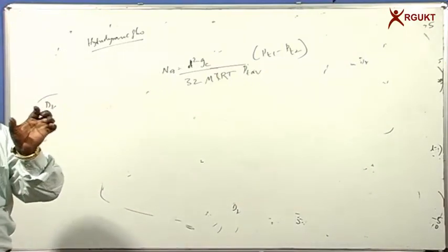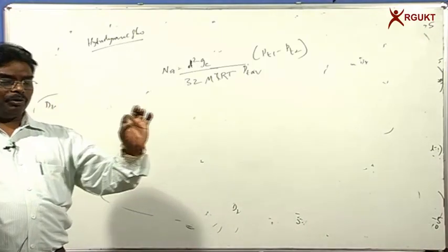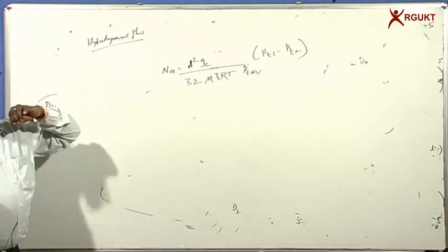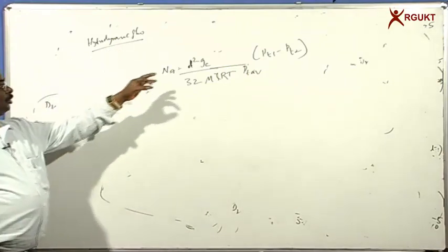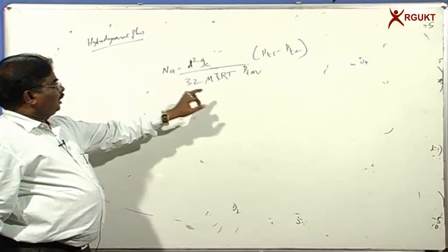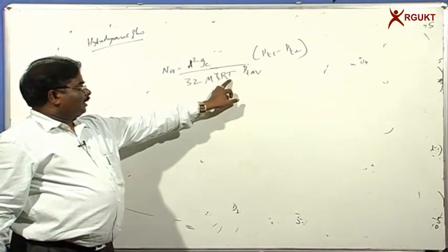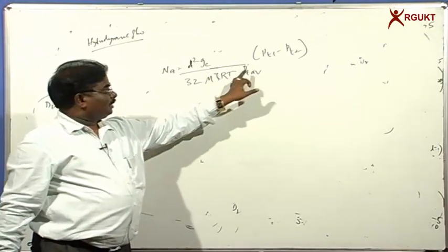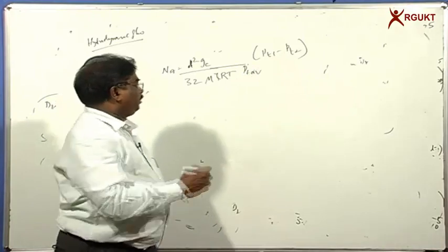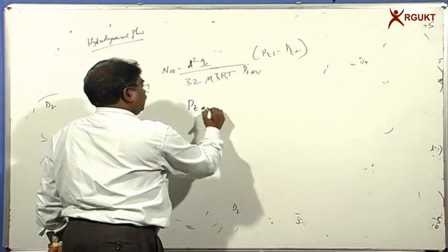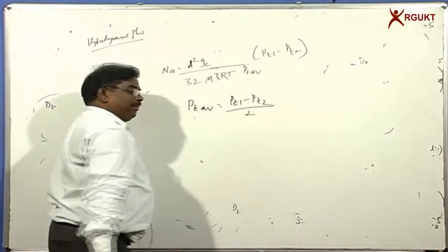The pore sizes are very, very big, and no diffusion is going to take place. The flow is taking place as if the pores are very big and as if it is a straight tube that we have. Here d is the diameter of the pore, mu is the viscosity, L is the pore length, R is the universal gas constant, T is the temperature, and P_T average is the average of the pressures P_T1 and P_T2, that is, (P_T1 plus P_T2) divided by 2.